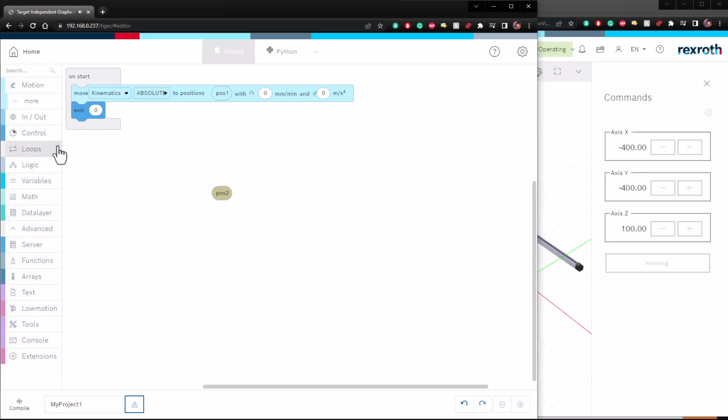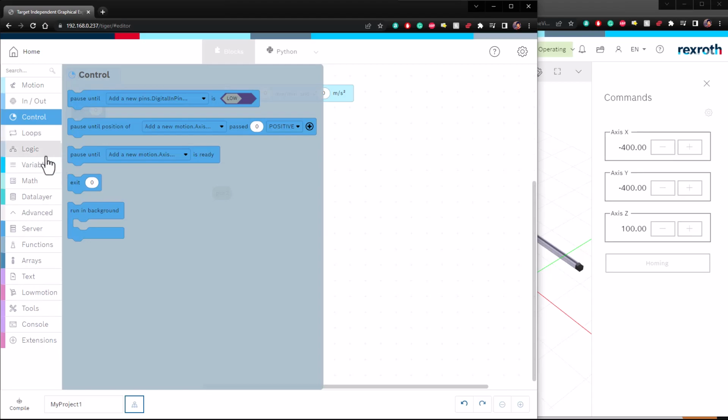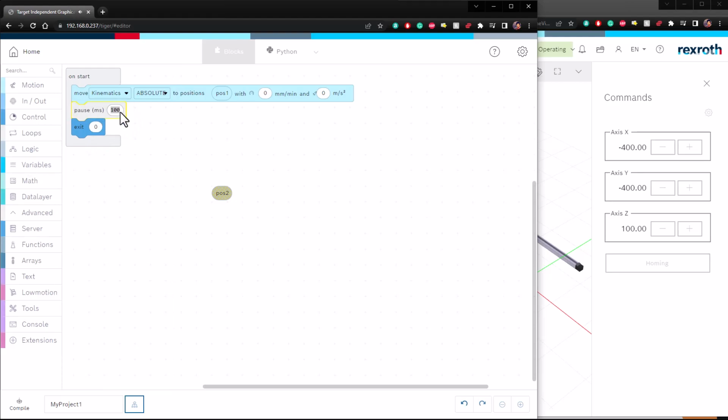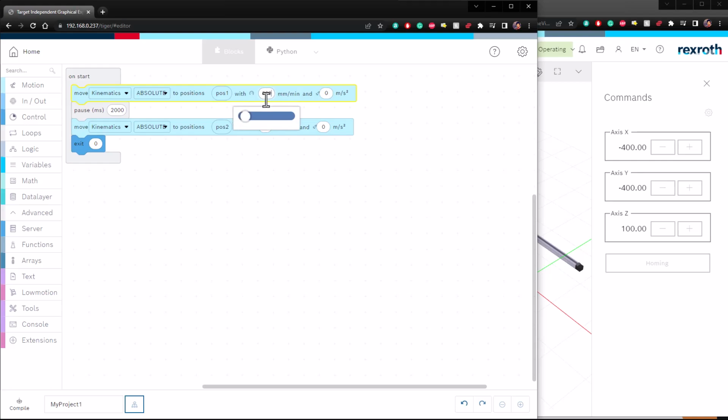And now I want to have a delay. Let's take a delay. In this case, I will go to my loop, take a delay, let's say 2 seconds. And I will copy paste this command, bring that here, and bring that to position 2. And here you can define the speed. Let's say I define 3000, and here I define 1000. All right. So here you can also define an acceleration. I will keep it to 1, and here 1 as well.